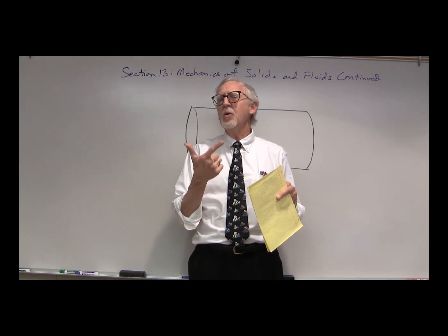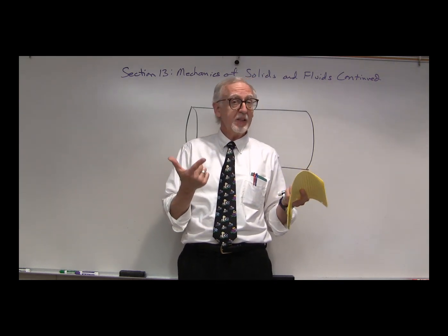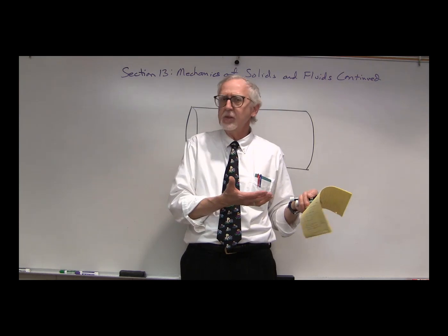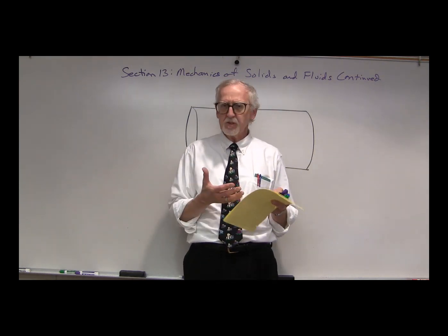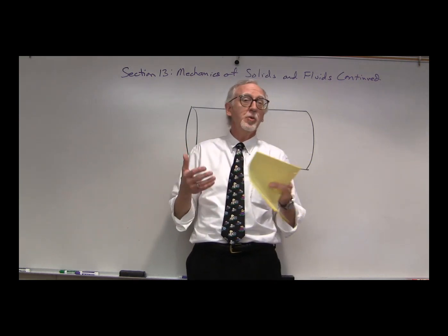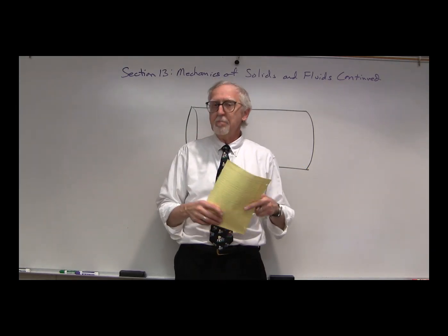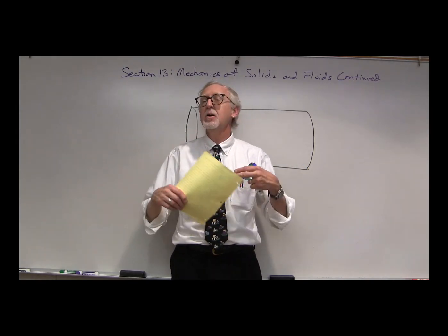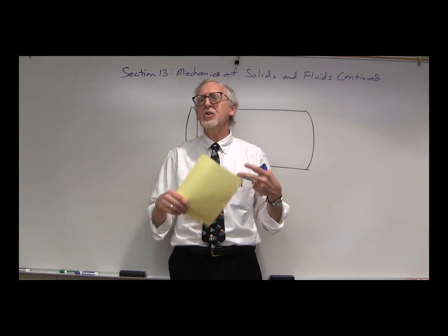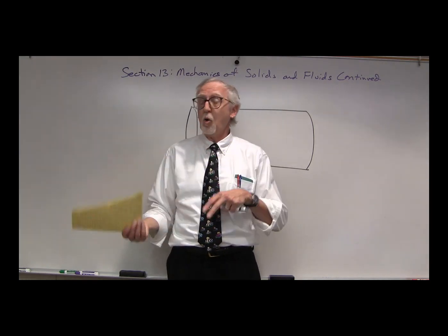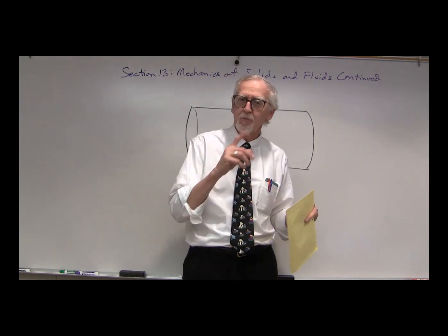Also, we assumed no energy loss, in other words, no viscosity. But obviously, fluids typically do have at least some viscosity. Some fluids have a lot of viscosity, and the more viscous or compressible the fluid is, the less accurate Bernoulli's equation will be. But it can still give us some very good qualitative results for different behaviors. Well, let's take a look at what happens when we do take into account viscosity or changes in density, the compressibility of the fluid. First, viscosity.